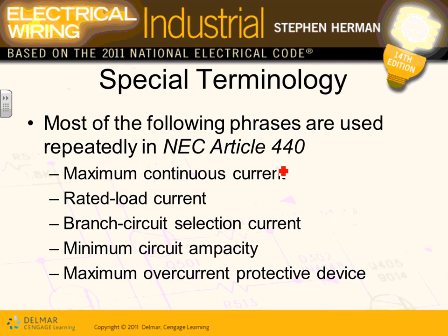Moving into the terminology. So that's your exhaust fans. Exhaust fans, guys, are easy because they're motors. Chillers. When it comes to chillers, any mechanical equipment that has a compressor in it, the NEC code book treats separately, differently, like we talked about before, and puts it in Article 440 instead of Article 430. Why? Because these guys are special.